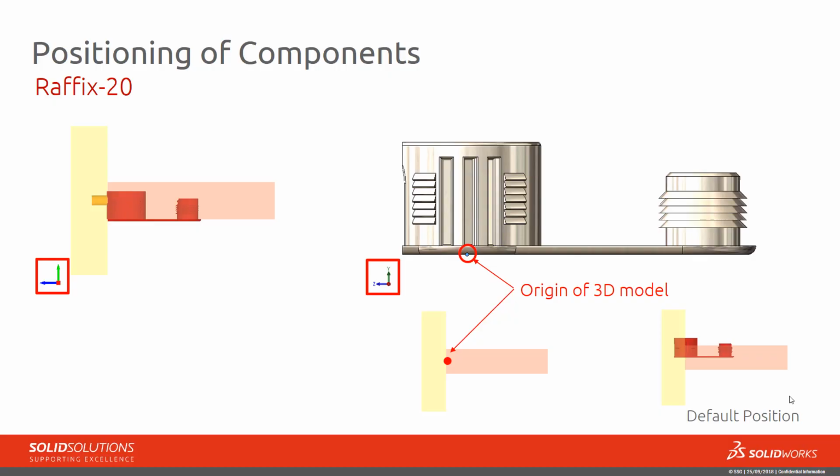The next goal is to add a connector item for each piece of hardware. It's important to recognize the location of the origin on your 3D model, as this will be the default location for the connector. So for this housing component, the origin is sat here where the blue circle is. So by default, the origin will sit central between the two panels, and therefore the default position of our connector would be what this image preview is showing here in the bottom right corner.